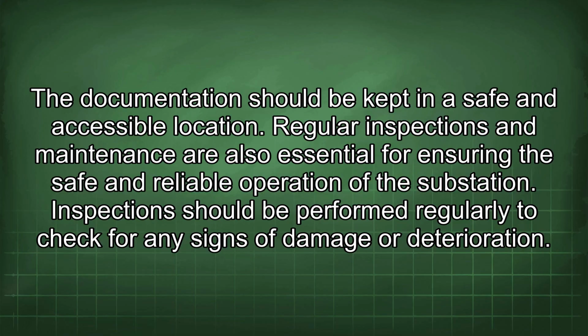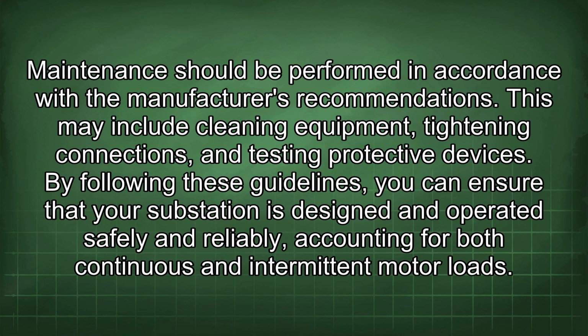Regular inspections and maintenance are also essential for ensuring the safe and reliable operation of the substation. Inspections should be performed regularly to check for any signs of damage or deterioration. Maintenance should be performed in accordance with the manufacturer's recommendations. This may include cleaning equipment, tightening connections, and testing protective devices.